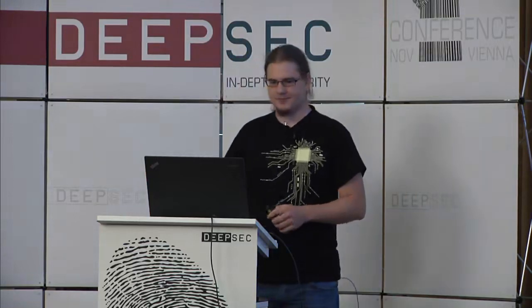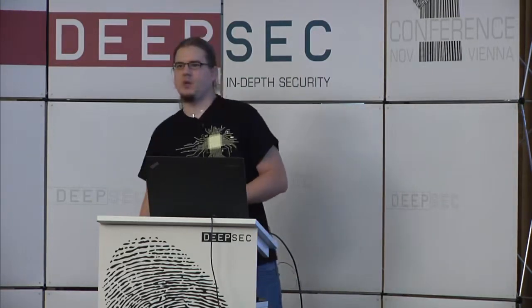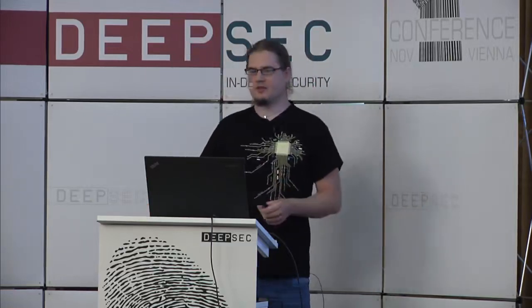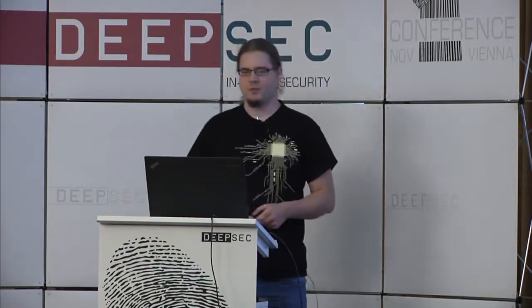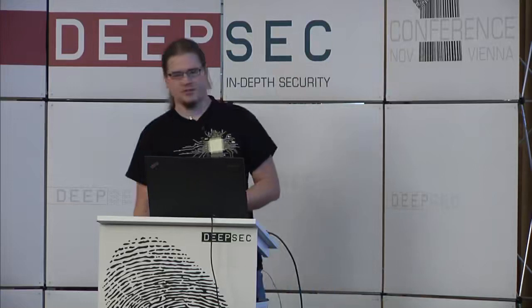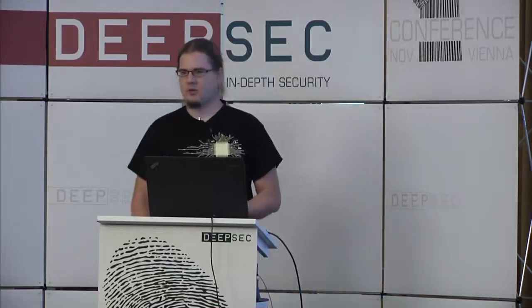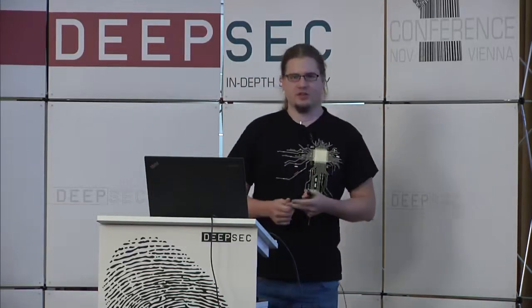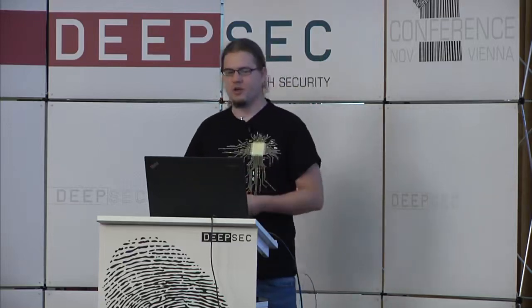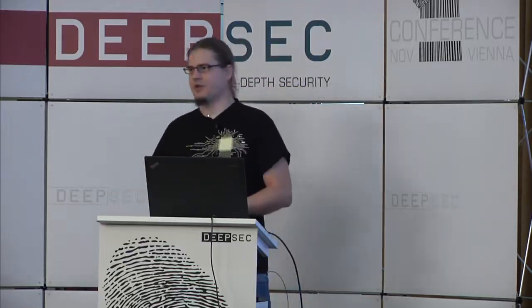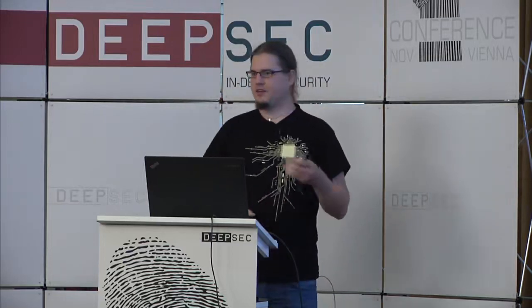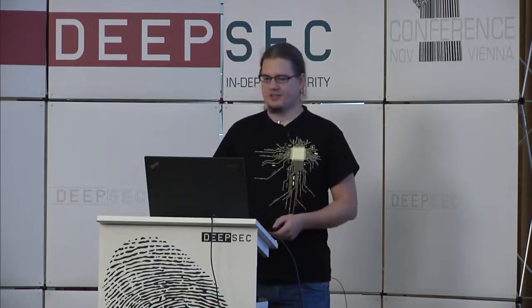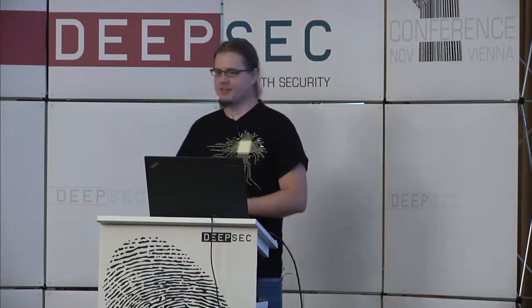So these are the keyboards. And I want to try to give you a quick overview of the testing methodology we use, the approach we take to analyze these keyboards. First of all, there's the hardware. We can open up the hardware, look at the PCB boards in there, and try to identify the chips on such a keyboard or dongle. If we identify the chips, we can read the manuals for those chips and find interesting test points. In this case, it was SPI. It might include soldering some wires or something like this for the firmware analysis.